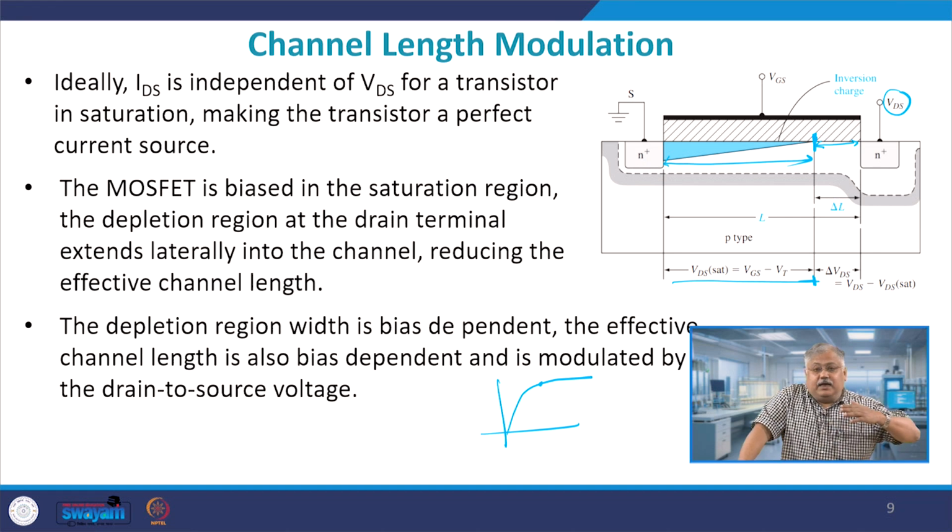When the inversion layer tapers exactly to the drain edge, we define that to be saturation. And you can see that as the value of VGS goes on increasing, the value of VDsat also goes on increasing. Why? Because as the value of VDS increases, the electric field increases, and therefore, you need a stronger overdrive voltage to saturate the channel.